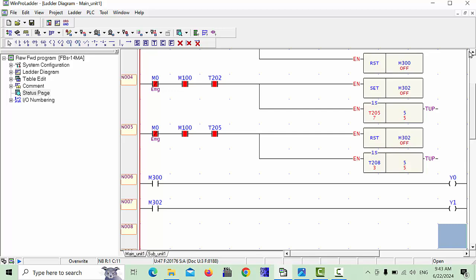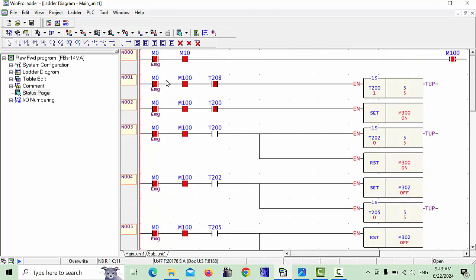Other signals also you can use in the program. Here you can put any other interlock, for example your door closing or opening. If you would like to add a function, you can make it here as a close contact. However many you use, you can use the signals in this row. I hope you completely understand this reverse forward program. You can use this program anywhere, for example in washing projects or some conveyors or whatever. It depends on your logic how you use the program.